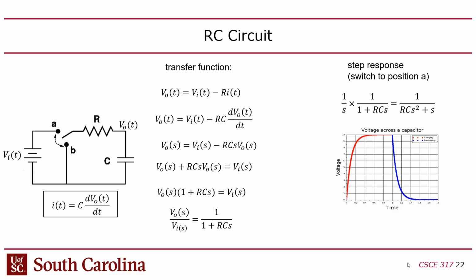That's what I expect to see, but that is not going to give me that, because remember, this is one of the rare cases where I can use an inverse Laplace. And what is the inverse Laplace of this? It's just an exponential, which means this is going to be unbounded, right? This is an exponential function, so I'm not going to get this from this. And I'm thinking, what the heck am I missing here? I don't understand this. This is definitely a bounded system, but yet I did the math that says it's unbounded. So what's going on? Well, it turns out I forgot to add the step.